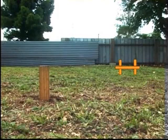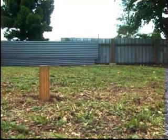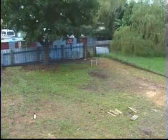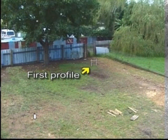Working from this established height, profiles can be erected with ledgers levelled in the one horizontal plane. This initial height peg procedure is needed because the first profile setup will not necessarily be at the high point of the site.